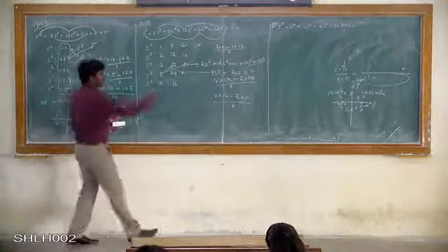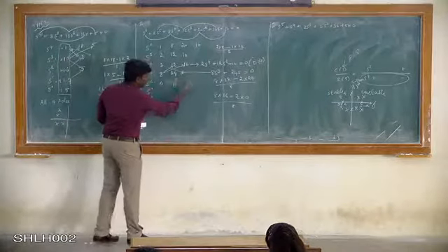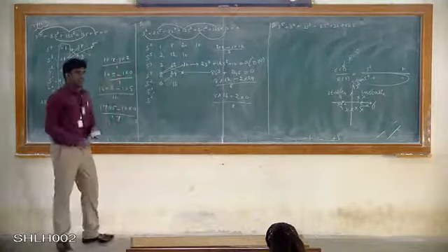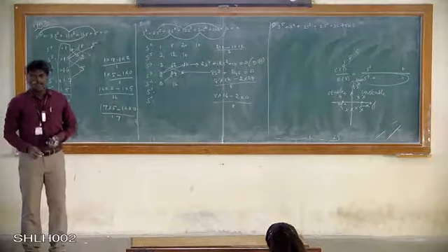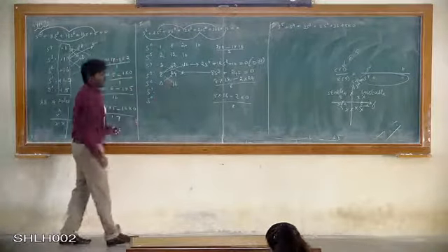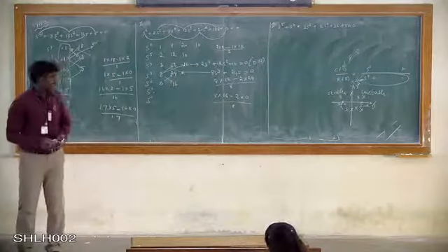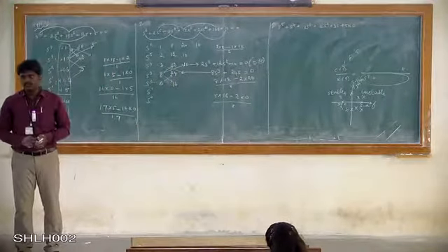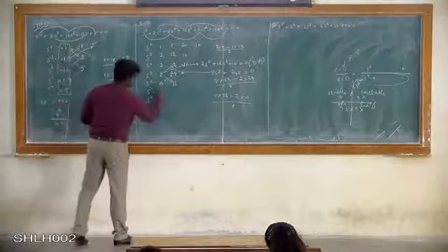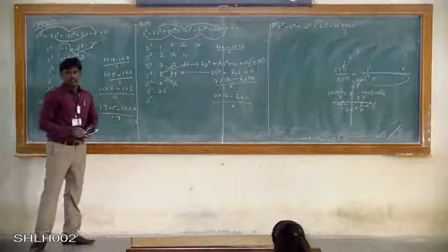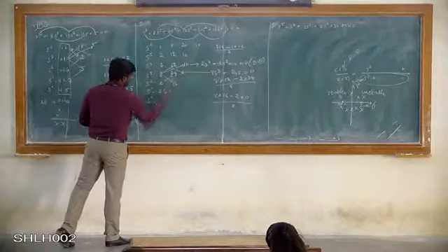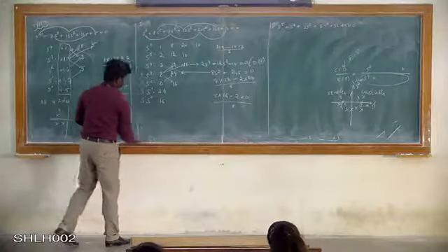Right? So now you don't have any other elements to get over here. Now go on solving for s power 1. Multiply 6 into 24 minus 8 into 16, divided by 6. You get 2.6. Next value, 2.6 into 16 divided by 2.6, it will be 16.